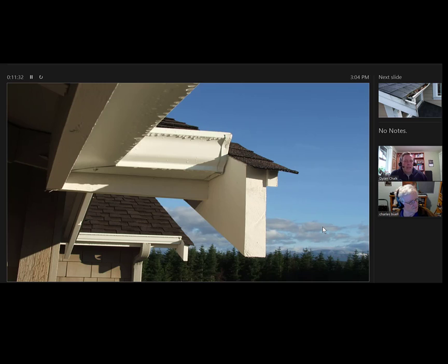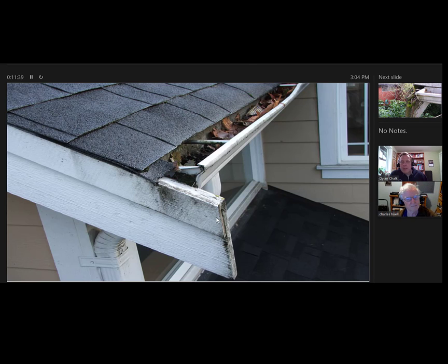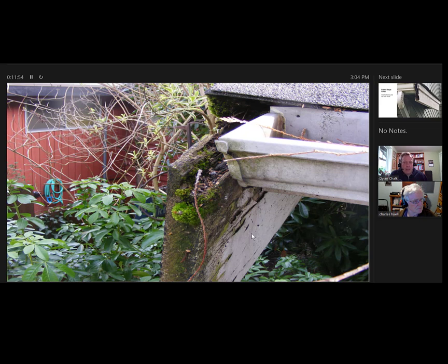In the picture we're looking at, you've got a roofing shingle protecting this piece of wood as it projects out past the gutter. But what tends to happen is the shingles get damaged or blow off in a windstorm, or people cleaning out their gutters, and then that little piece of barge rafter or fascia gets exposed to the weather, and then you wait 30 years and it all rots out, right? Yeah, or 5 years for whitewood. That's right, that spruce will rot in no time. So it's a common repair item.